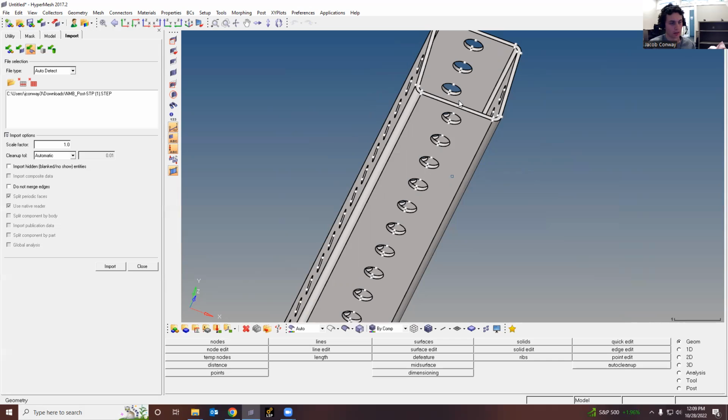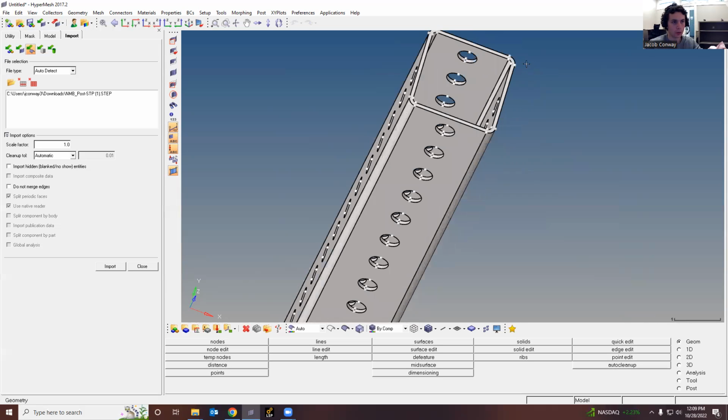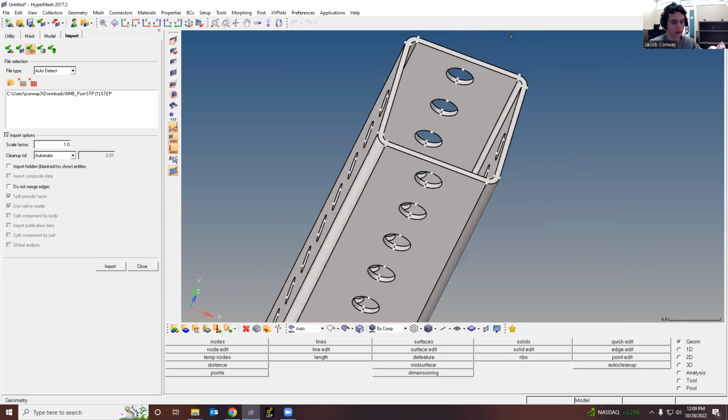So for this PSST, we're actually going to mesh it as a shell element, which means it's not going to have a thickness. It's just going to be the shape, which will be at the mid surface of what this would be. And then in pre-post or something else, we would actually have that thickness as a part of it. So if you've watched the lectures from Cody in lecture 10, he goes over shell elements.